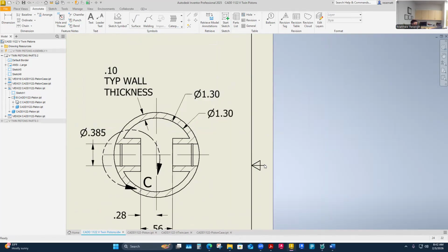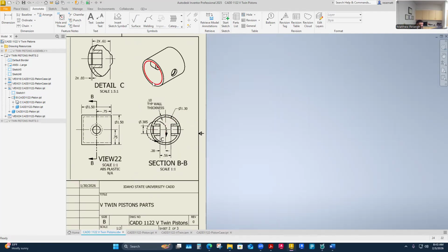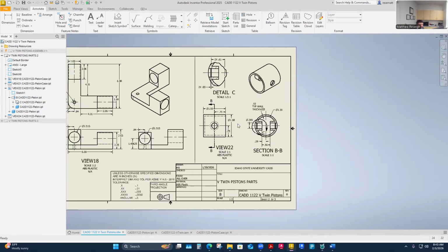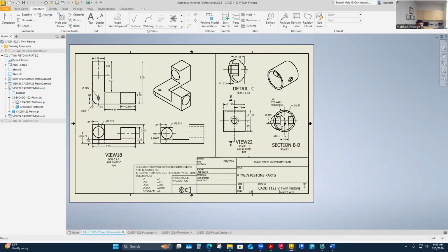Technically, it is a radius, but maybe I just want a diameter to display because it's the inner diameter of the piston. I think it's arguable that either one could probably be okay, though. It is a portion of a circle there, actually. So, except for out on the very end right here, it would have accepted that. If it was a true end view of that, it would have accepted that as a diameter. So I changed mine to diameter. And then I think that was it for that little part. So I've got that one modified, dimension updated, kind of like my view label sizes.